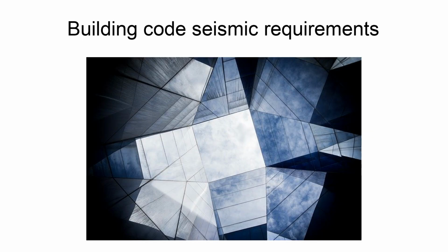The most current building code enforced in most jurisdictions in the United States is the 2006 International Building Code, IBC, 2006. The 2006 IBC references the 2005 edition of the Standard Minimum Design Loads for Buildings and Other Structures prepared by the American Society of Civil Engineers, ASCE, 2005, for its seismic provisions. ASCE 7-05 contains specific requirements for non-structural components including requirements for architectural glass.